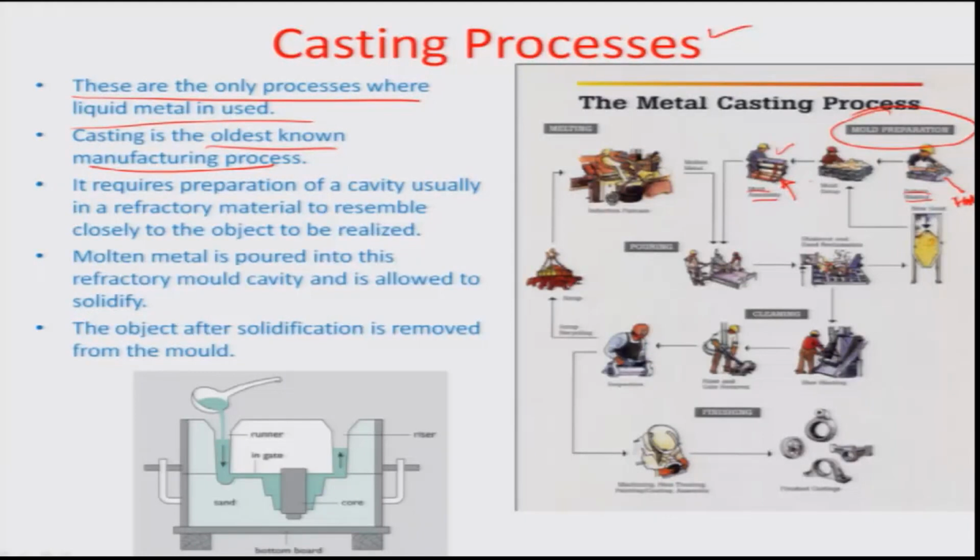So once you do that, then obviously you have something called a mold. Now the mold has, in addition to the pattern, several other regions which are very important for the metal transfer process. So there is a liquid metal that you are pouring, so you have to run the metal through a substantial section of the mold before it enters the pattern, so that the momentum, etc., is reduced and the mold does not get damaged.